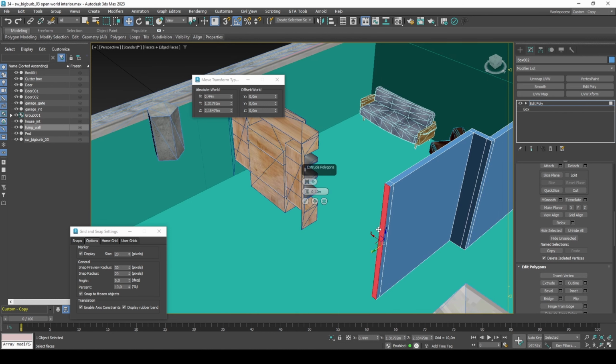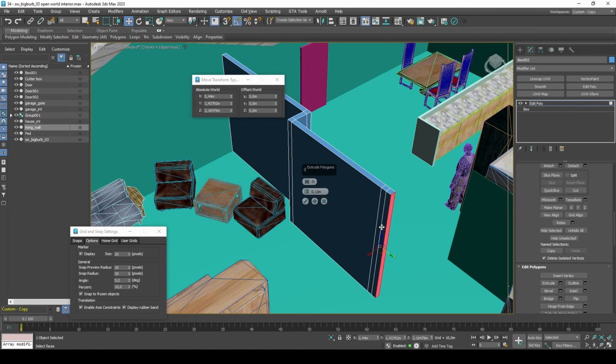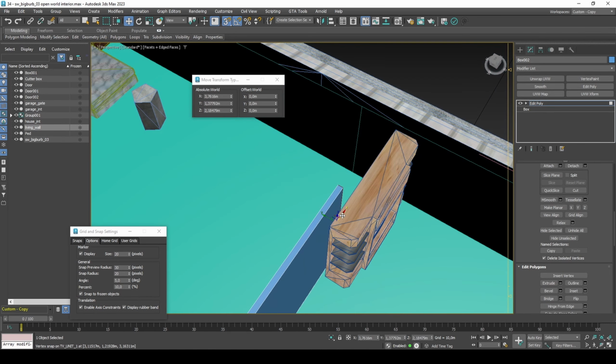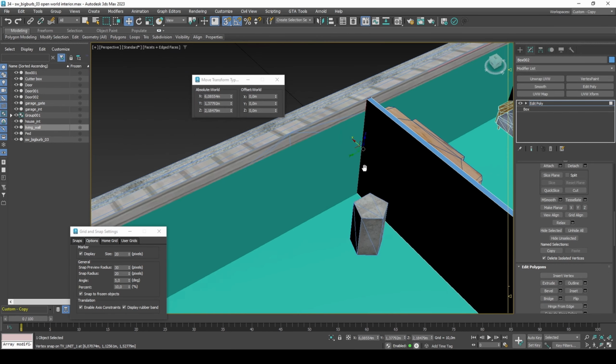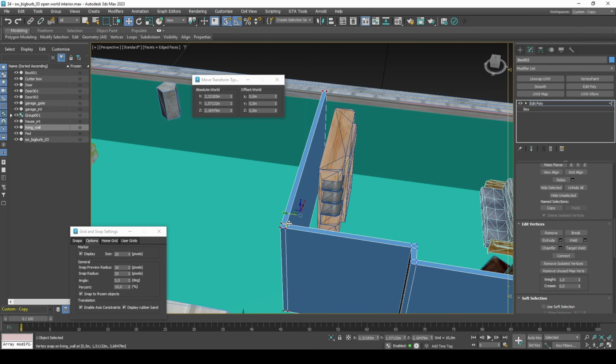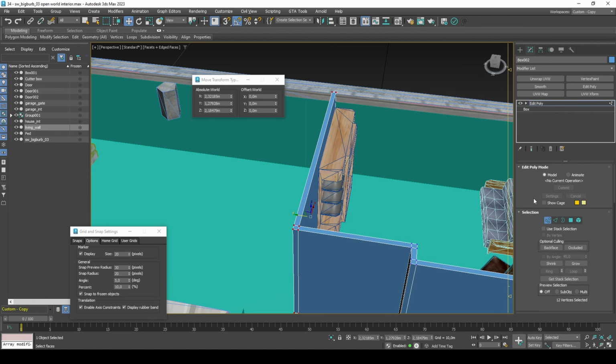Extrude and extrude again and point it towards the living room. Constrain it to the living room wall to close off the room. Select the wall vertices that is adjacent to the TV unit, and snap them to the back of the TV unit using axis constraints. Move the top faces of the wall up way above the ceiling and convert to Boolean.